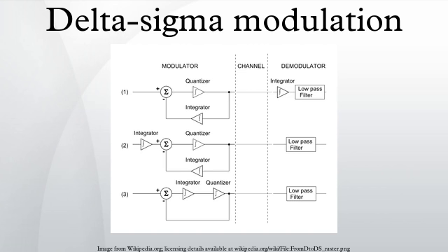Analog to digital conversion. Description: the ADC generates a pulse stream in which the frequency of pulses in the stream is proportional to the analog voltage input, where K is a constant for the particular implementation. A counter sums the number of pulses that occur in a predetermined period, so that the digital display of the count is a display of the input voltage with a predetermined scaling factor. Because the counting period may take any designed value, it may be made large enough to give any desired resolution or accuracy.